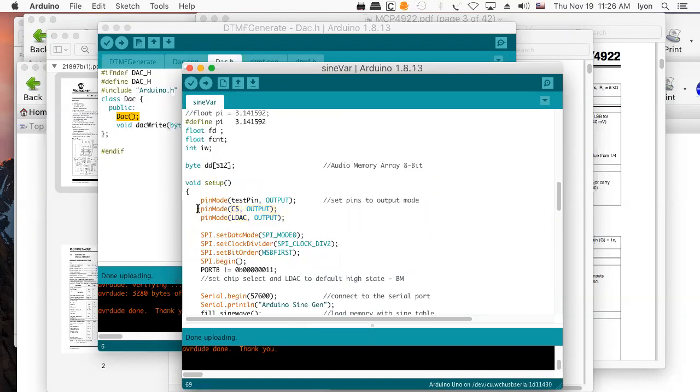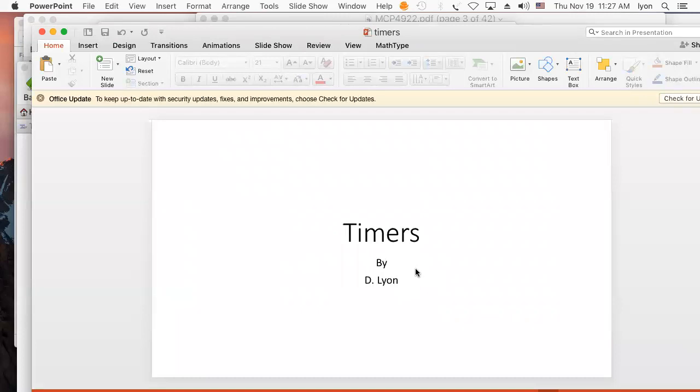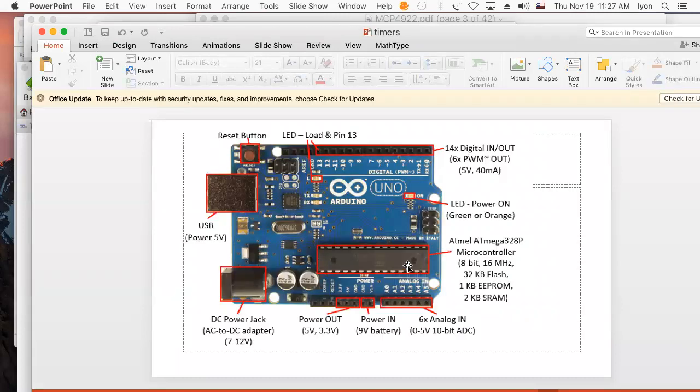So this is actually a way to manipulate one of the pins, one of the bits in the data direction register. When you look at the Arduino, you're going to wonder, where's pin 8 and where's pin 9 on the data direction register? There's a couple ways you can go on that if you're wondering what pins are which. Here's the Arduino. Here's the pins. There's 8 and 9 coming right out. These are digital I/O pins, so you can see that's probably where the DAC is wired. And if you're ever wondering, you could always just use a continuity checker and make sure.